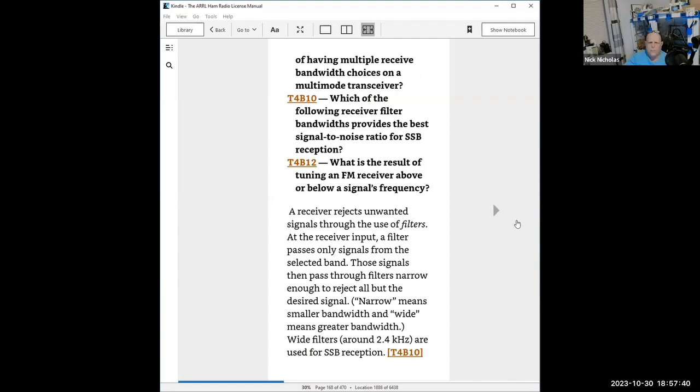And so when we bring in that noise, the next trick is we've got to get rid of it. I already covered how we did it digitally, but we use filters, whether they're digital or analog, to filter out what we don't want. There are several types of filters. One is the bandwidth filter. A bandwidth filter narrows how wide the receiver will hear. It narrows the band. A narrow bandwidth filter is very, very small in value.